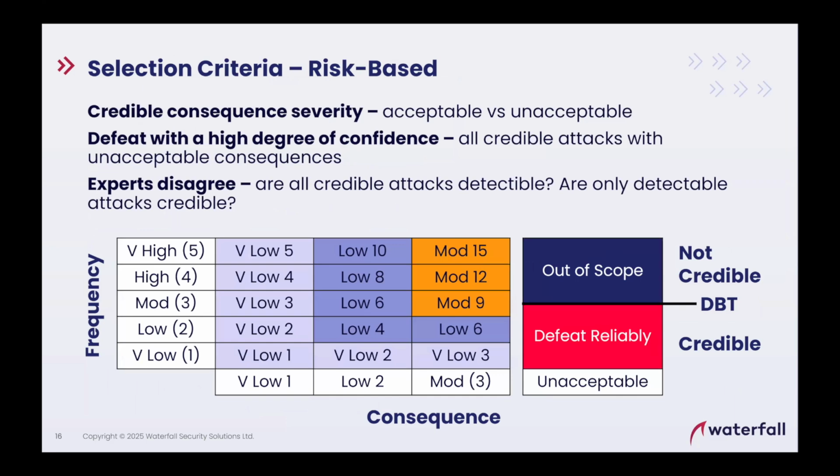When we do this risk assessment and the worst case consequence is acceptable, we can use frequency and severity, a traditional risk matrix, and evaluate the security of the remote access against the matrix. Bluntly, if we have only acceptable consequences, we can probably buy insurance to cover that. Which remote access should we use? The one the insurer recommends, because they're the ones who have accepted the risk. Do what the insurer tells us, and they will cover us if we're breached.